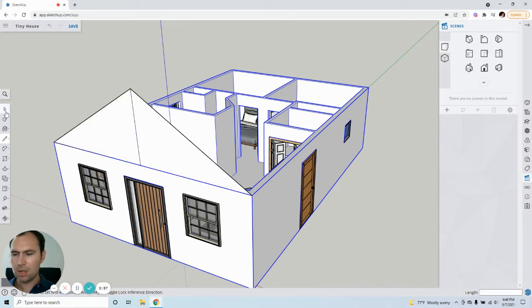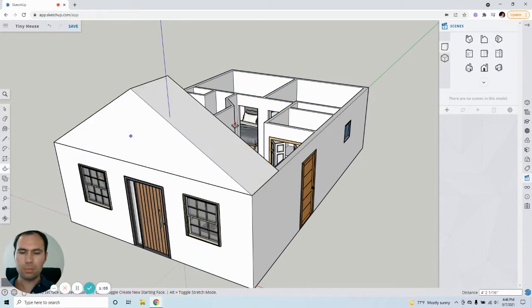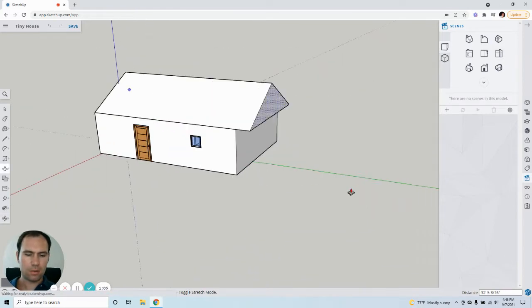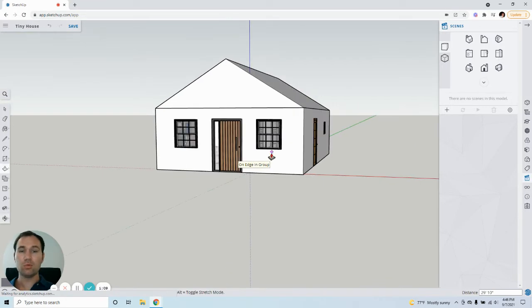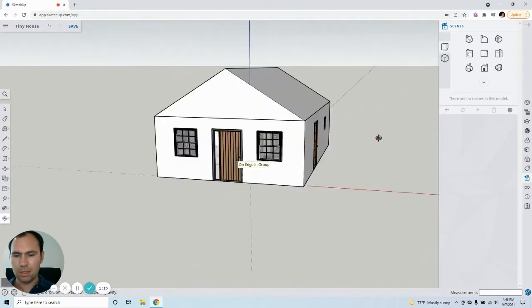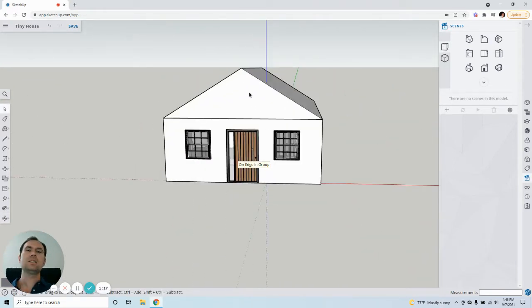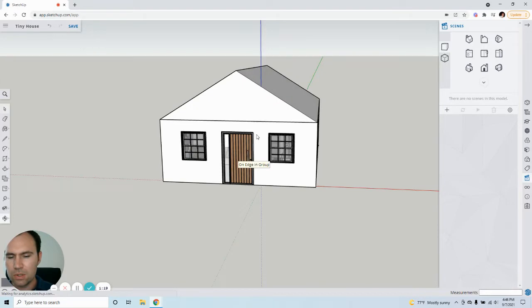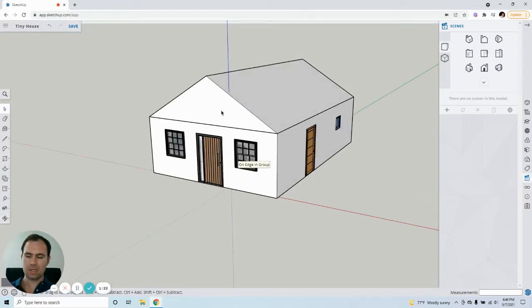Complete the shape, you get a triangle. Next, delete the center line you used to create the height and push P to push pull, orbit around, bring it into the outer face. Boom, roof. Now, drawbacks. It's very basic, very limited in details, and I'm going to show you what those details are and how we can actually get around it. So that's the first one.